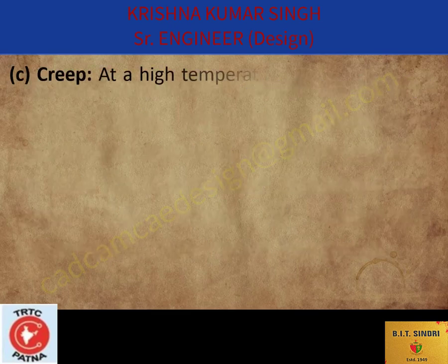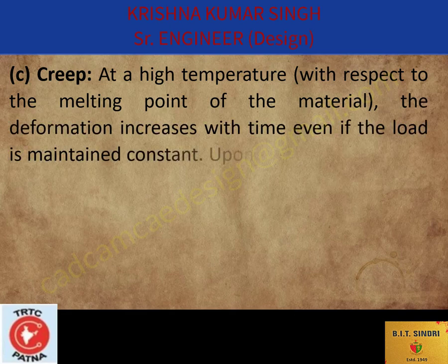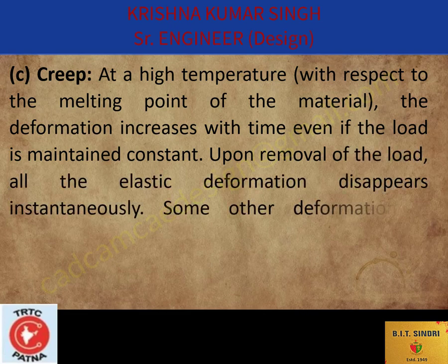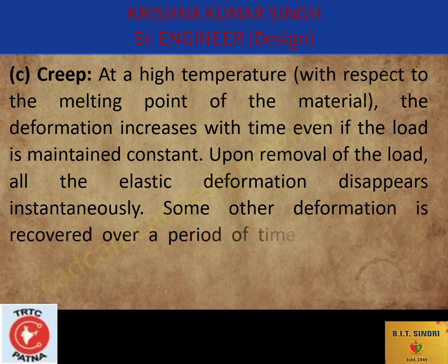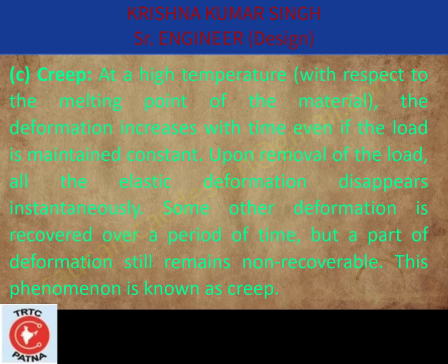The next is creep. At a high temperature with respect to the melting point of the material, the deformation increases with time even if the load is maintained constant. Upon removal of the load, all the elastic deformation disappears instantaneously. Some other deformation is recovered over a period of time, but a part of the deformation still remains non-recoverable. This phenomenon is known as creep.